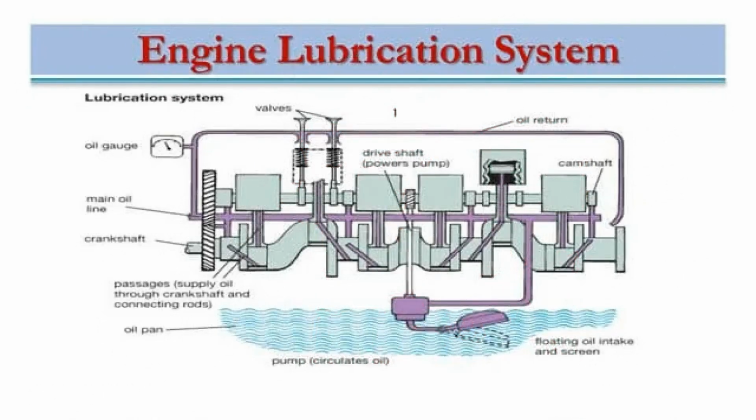An oil pump is present in most modern engines. It is not always rational to expend engine power to support the high pressure required to lubricate all the engine parts that need it. Therefore, where it is possible, the method of splashing is used, when the oil flows to the rotating parts and splashes all over the volume of the cavity, creating a dense oil mist, enveloping everything around it. It should be noted that the splashing method has many disadvantages.